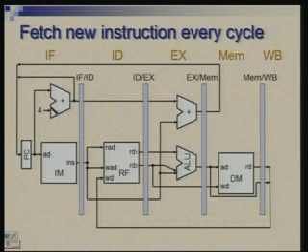Let us just turn our eyes away from that and imagine that we have instructions like load, store, add, subtract and SLT and so on, and for quite some time we do not have the BEQ instruction. So, as long as we keep that away, we have a possibility of being ready with PC plus 4 in every cycle. So, therefore, this part is really now geared to pump in a new instruction every cycle. Okay, is that part clear? Okay.